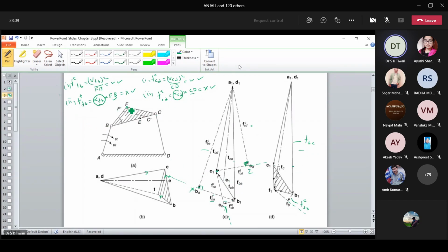Now in the second go, when F is rotating with C as the center of rotation, I will find FC. That will be velocity of F with respect to C square divided by FC. Velocity of F with respect to C, this is the vector. It means you know the magnitude, you know the direction. The second component will be Ft, Fc. Since it is equal to alpha Fc into Fc, you are not knowing about this acceleration. It means half-baked information. You don't know the magnitude, you know the direction.